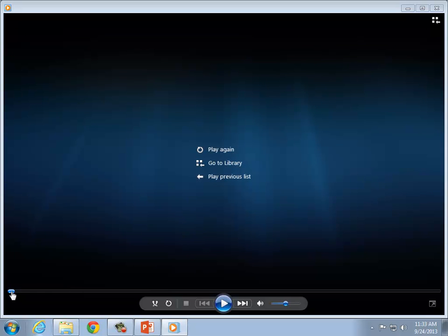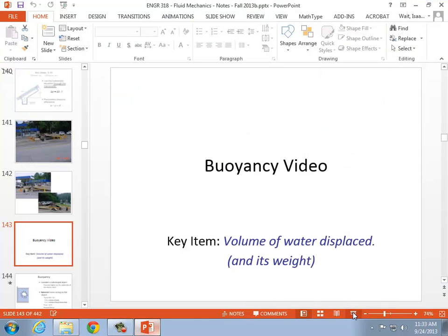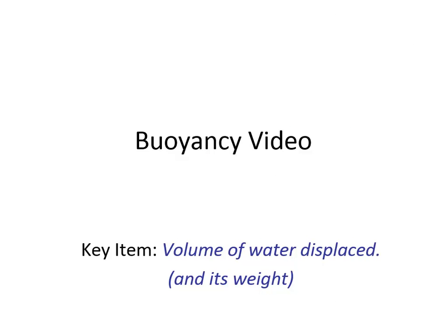Okay, very good. So maybe just information that you already had is that a submarine controls its buoyancy by having extra water on board. If we had a cross section of the submarine, since there's a void inside of the submarine, this is the passenger compartment here on the inside, they've got some extra water in there, so that they can control the overall buoyancy of the submarine as a whole by increasing or decreasing the amount of water that's inside there, by pumping it out.